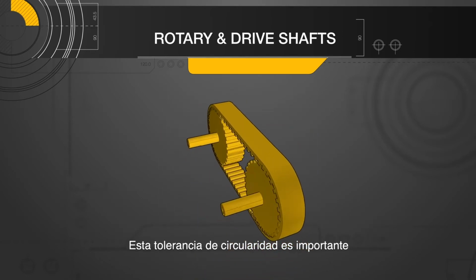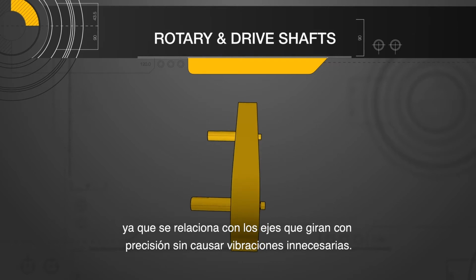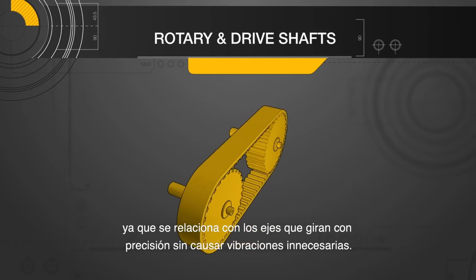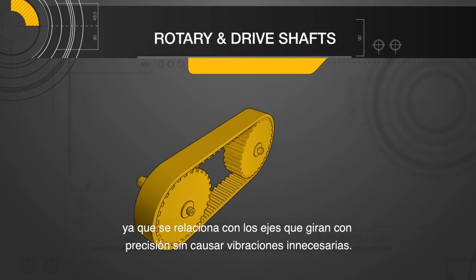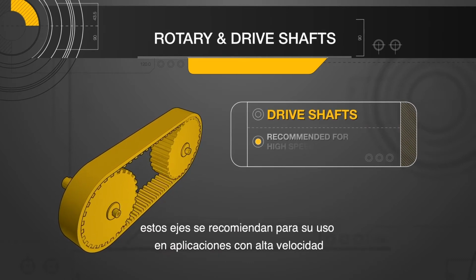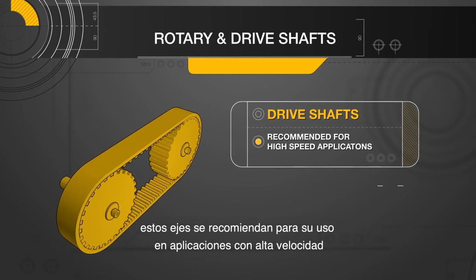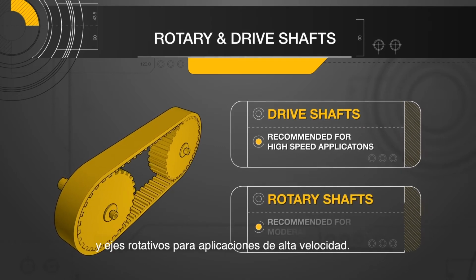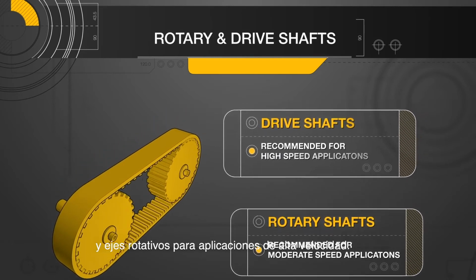This circularity tolerance is important as it relates to the shafts rotating accurately without causing unnecessary vibration. Since drive shafts have a higher tolerance, these shafts are recommended for use in applications with high speed, and rotary shafts for moderate speed applications.